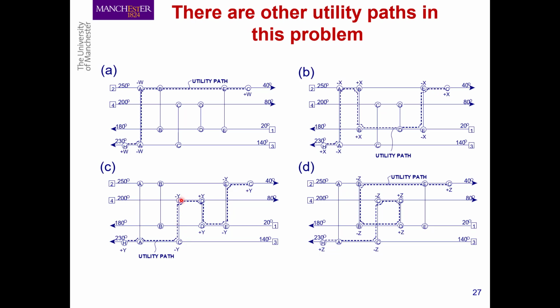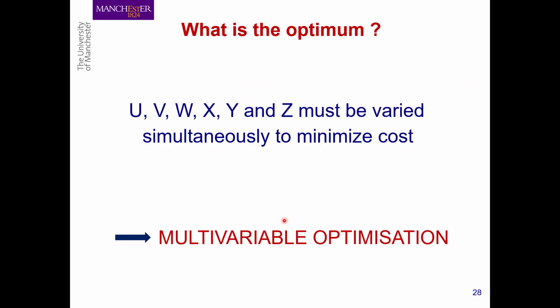The goal is to shift the heat duties and then change the temperatures, and as such minimize the overall area of all these exchangers in this utility path. So what we are trying to optimize is the values of these different heat duties along either a utility loop or a pathway or just a utility path. So by optimizing or by shifting these heat loads between different units along a utility path or in a loop, we can actually minimize our overall area of that system.